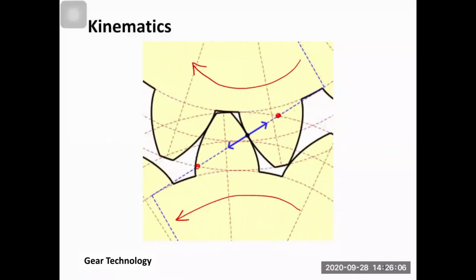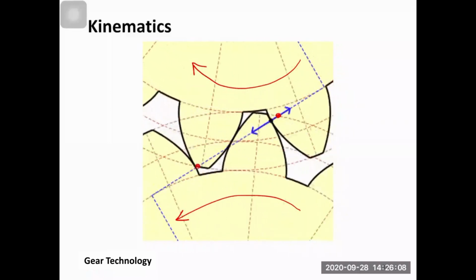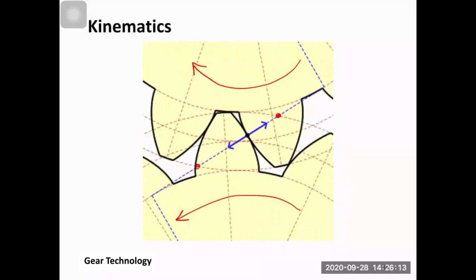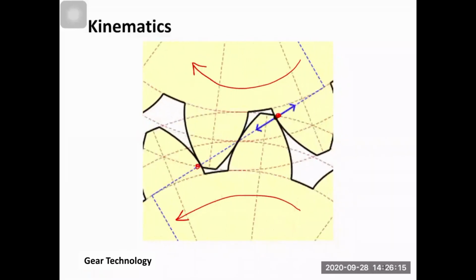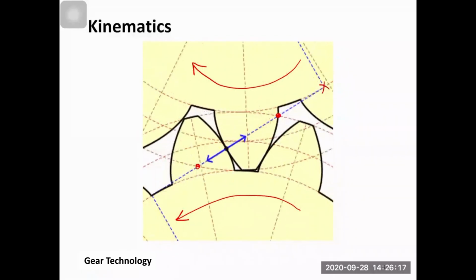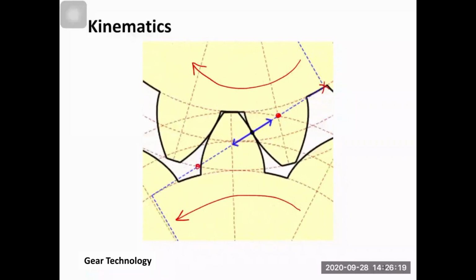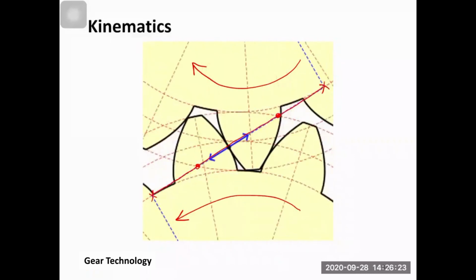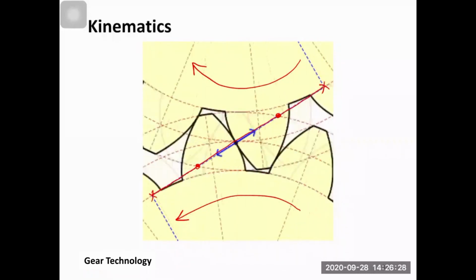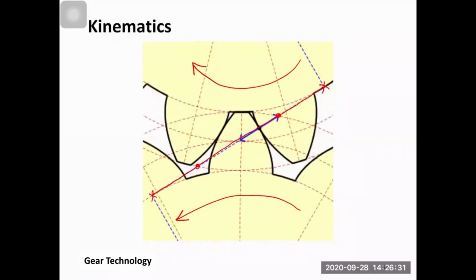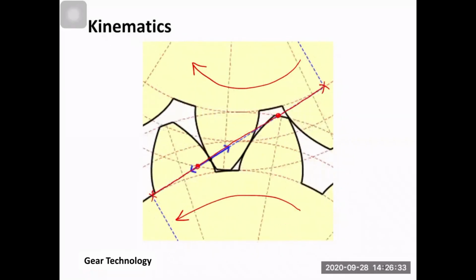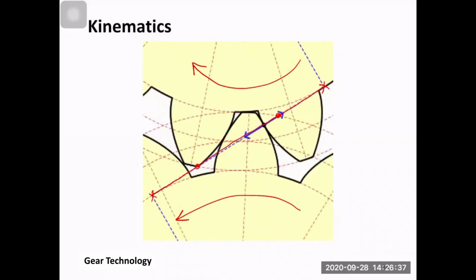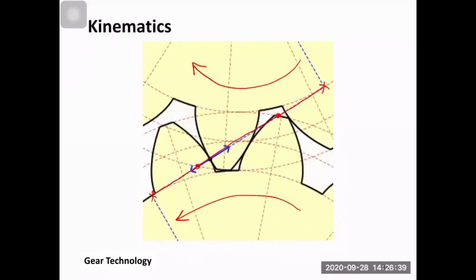Yeah. So you see here that because of the involute curve or the involute profile, they offer constant speed ratio. And then this line between this point and this point is the line of action, where the action happens, where the two gears start engaging. And these two arrows show you the forces between them. They push each other, they apply force on each other.